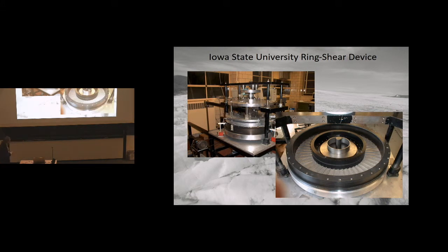This is the sample chamber where the till sits. And this is about 60 centimeters from here over to here. We don't use an intact till sample. That would be very difficult to collect. We put a disturbed till sample in here. We saturate it with water, and that water is connected to this interior reservoir through some channels that you can't see here. And that reservoir is kept at atmospheric pressure. So this is a so-called drained experiment in the vernacular of geotechnical engineering.